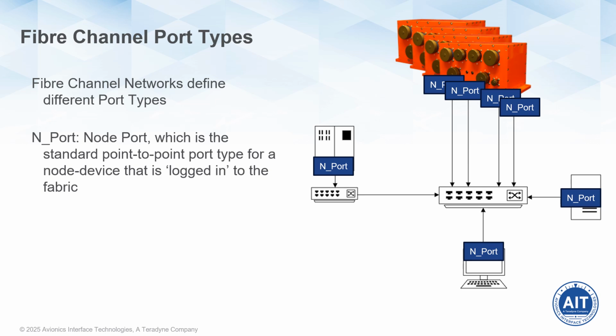In the situation pictured, nodes will generally log into the switch fabric to receive their address, but it's also possible to implicitly log on to the network. An implicit login would be when the node knows what its port address is going to be without actually going through the process of logging in. Most avionics networks do use implicit login with a pre-programmed port configuration in order to reduce latency, especially between power disruptions, but also just to get up into an operational state.